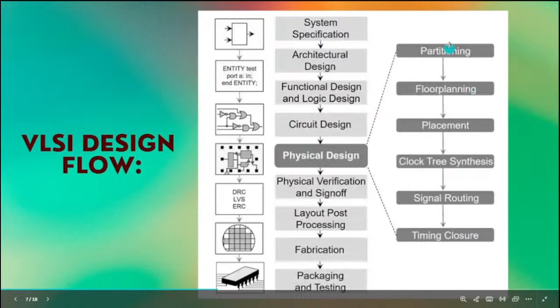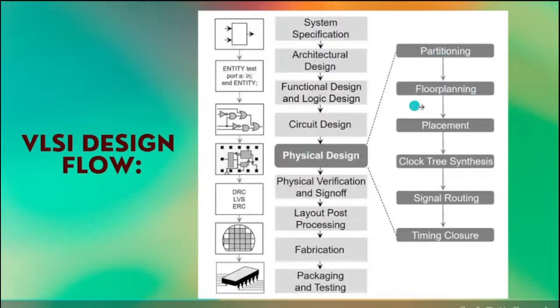So these are the steps, like partitioning and floor planning. Floor planning is nothing but assigning the memory blocks, DSP blocks, counter blocks or GPU blocks. They are planning which part of the chip each must be placed in. I will show it in the upcoming slides.